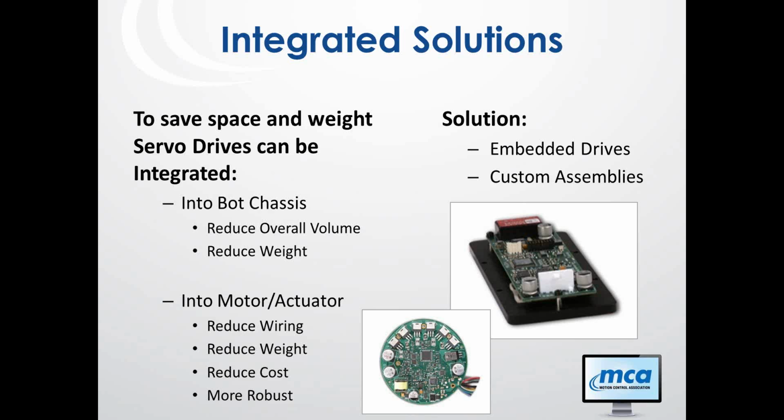And not only does it have the servo drive control, it also has the controller and communications front end built into it. So you're merging sub-assemblies, and you're taking the servo and putting it right in the back of the motor. So all you have is wires going from the drive to the motor phases itself. The feedback is done magnetically, so there's no wiring for the feedback. And the only wiring coming into the motor drive assembly is power and communication. So you really minimize the wiring needed for this application, and you achieve a lot of the goals that we've been looking for in a mobile platform.